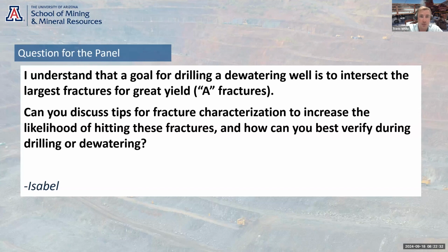But the drill chips normally indicate a little bit in advance of the structure. And depending on what geology you're drilling through, there are some indicator minerals that will show signs of water, like your iron carbonates, calcites, things like that. Especially in your karstic aquifers, those carbonate minerals will precipitate out, and you'll get them coming up in the drill chips.